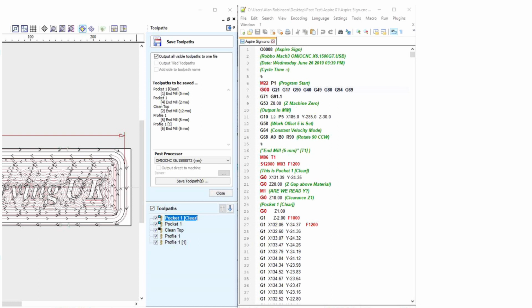G43, G44 and G49 tool length offsets. To use a tool length offset, program G43H, where the H number is the desired index in the tool table. It is expected that all entries in this table will be positive. The H number should be, but does not have to be, the same as the slot number of the tool